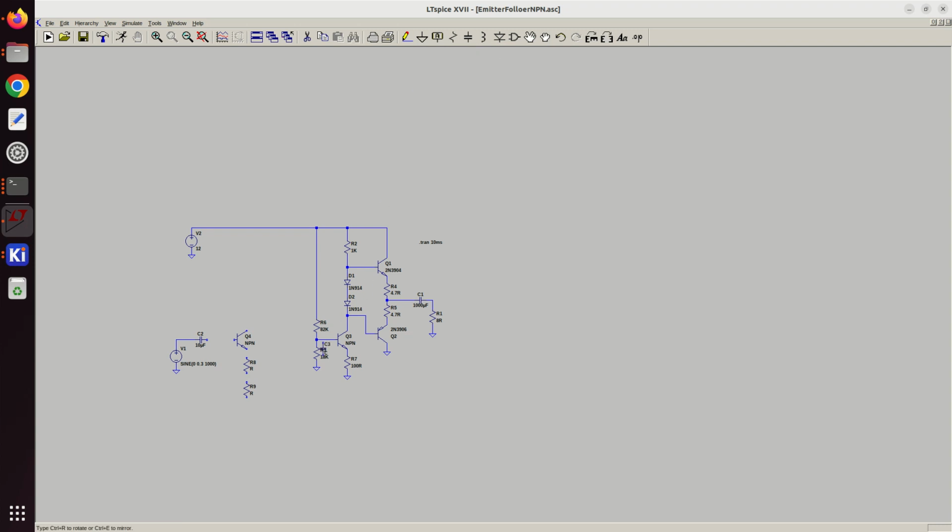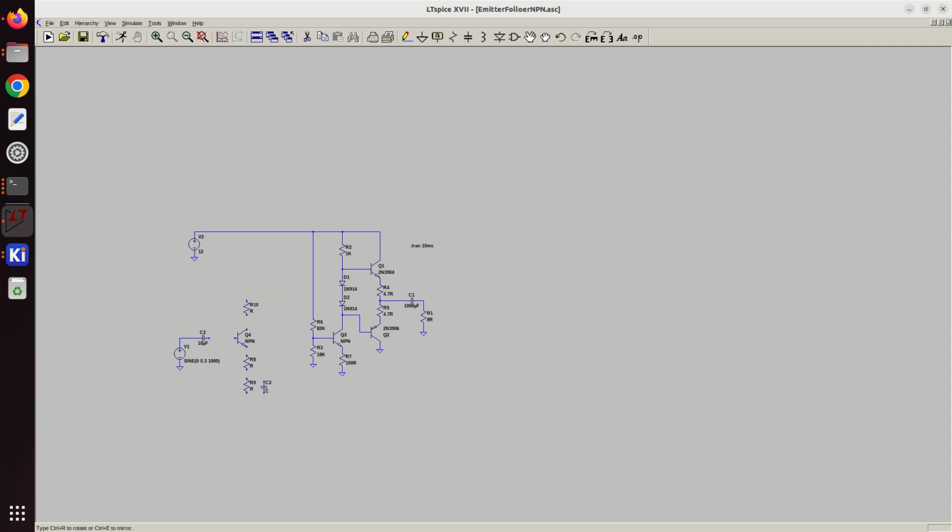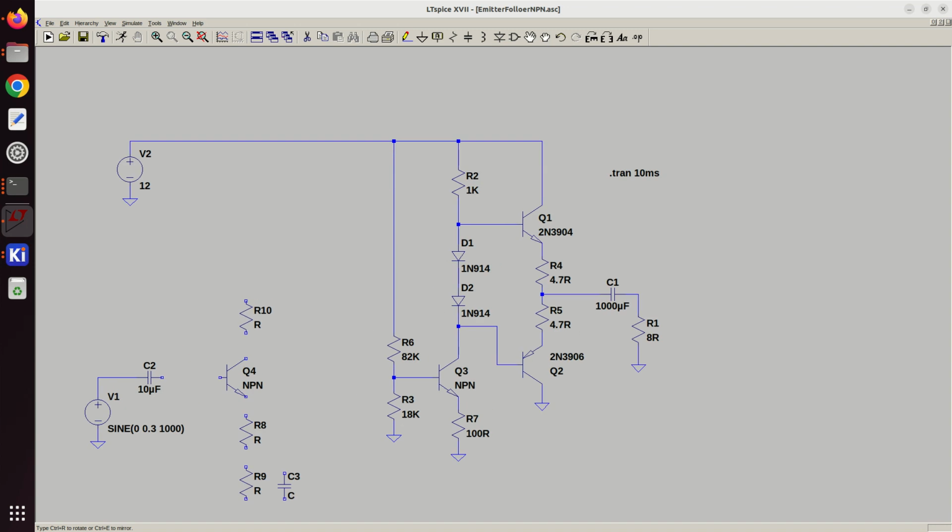I'm going to put one capacitor, and this is going to allow us to basically vary the gain of this guy nicely, and another resistor here, and we want to bias this as well. Okay, so let's connect this guy up. So this can go straight to the base. And again, we'll bias this and we'll just play with it.